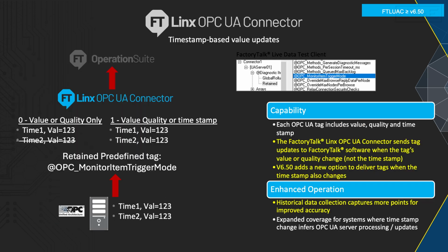One of the things with an OPC UA connector is typically it would send data point values, or update the data point values, whenever two things happen: the value or the quality of the data changed, right? So if you were subscribing to it, oh, I need to get it now because I subscribed to the data point. Well, there's been a new one which you can actually get on time change. So if there's a time change associated with that from the source, then it gets signaled, hey, you need to pick this up because there's a new update. Why is this important? For historical data collection, right? Because you're driving that off time, not off the value changing.